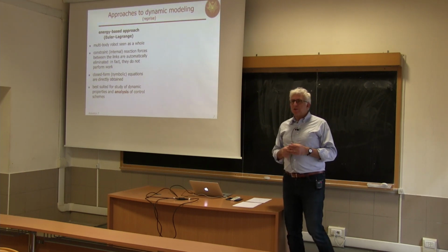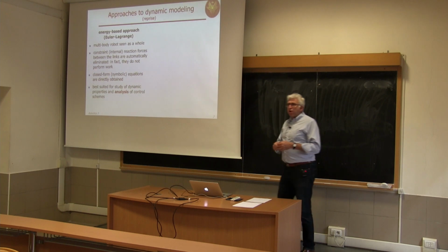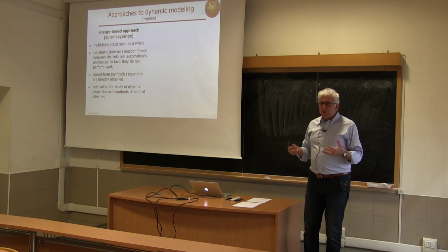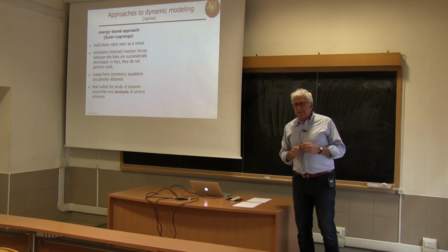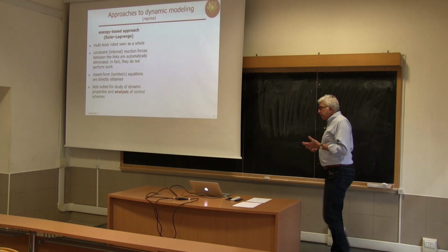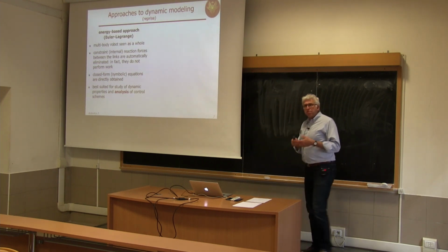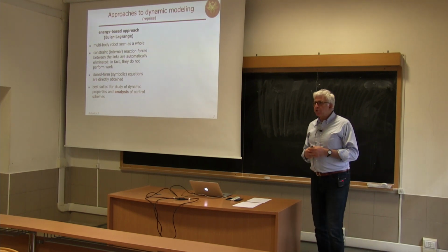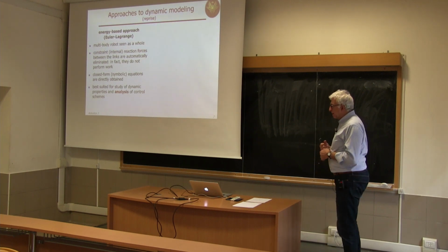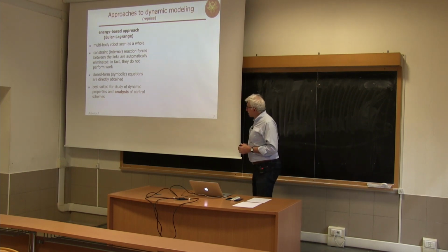Similarly, from conservation of energy, we have seen that M dot minus 2S, for any factorization matrix S of the Coriolis and centrifugal term, will vanish when put in a quadratic form where the external vector is the same q dot which appears in the internal matrices. This is another fundamental property from physics that will be used, for instance, for proving that a very simple PD control allows global stabilization of any desired equilibrium state in the absence of gravity, one of the first basic control results that we will see later on.